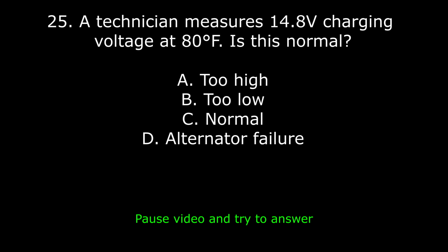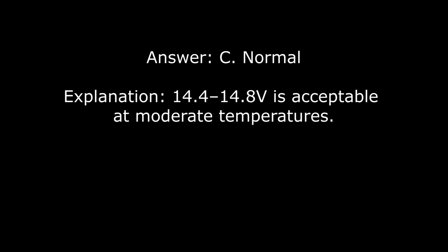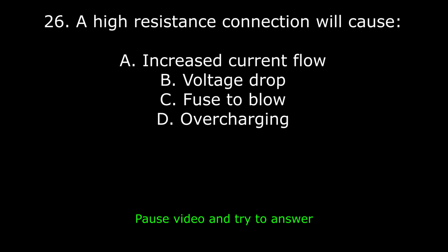25. A technician measures 14.8 volts charging voltage at 80 degrees Fahrenheit. Is this normal? A, too high. B, too low. C, normal. D, alternator failure. Answer C, normal. Explanation: 14.4 to 14.8 volts is acceptable at moderate temperatures.